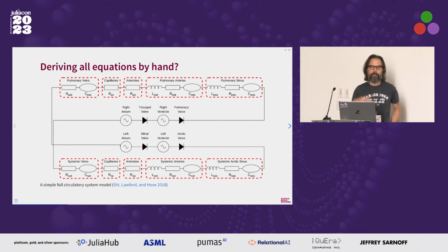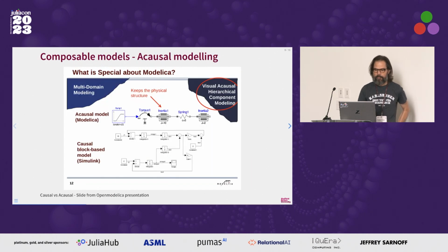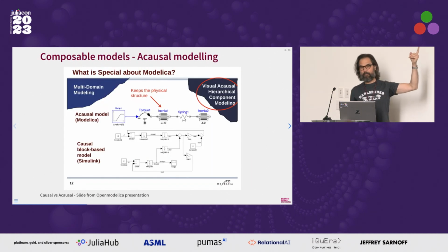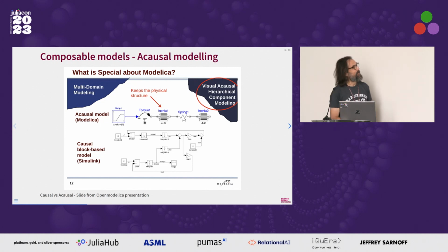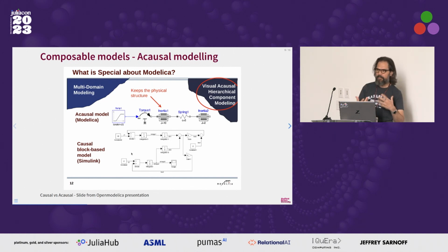So, that's where acausal modeling comes into this. I stole this from the competition, OpenModelica, their presentation. If you know Simulink, then yes, once you have the ODEs, you can put a kind of modular system together, but I'm not a Simulink user, I never really grew into that, because it's basically setting up a block diagram or an algorithm to solve the ODE rather than setting up the ODEs themselves.